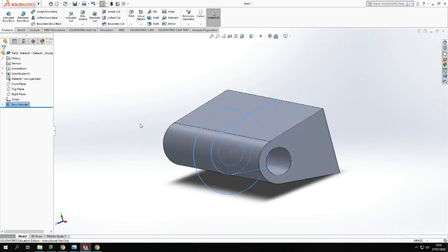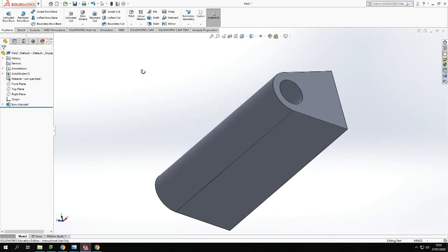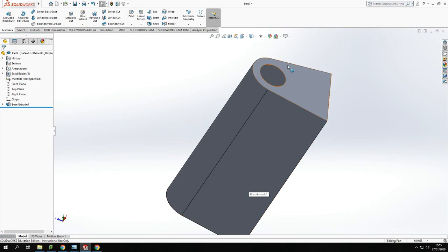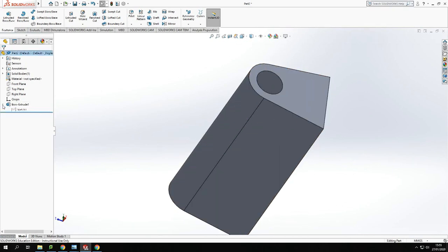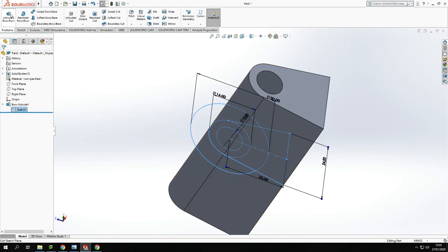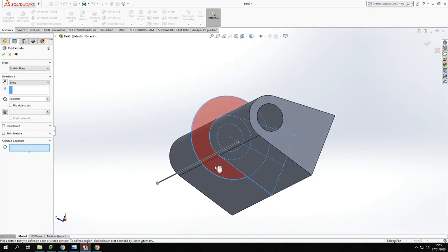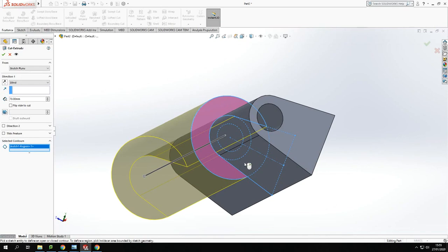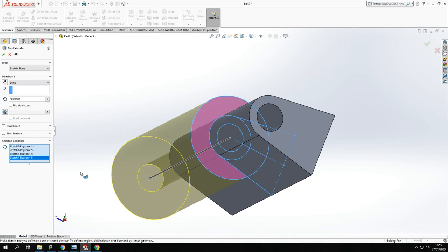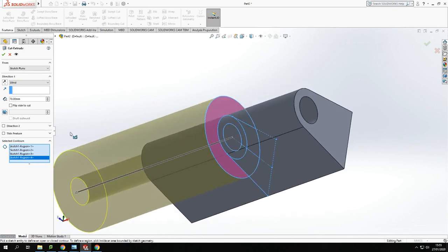and tick that. Okay, so what I've got now is the bar, a single bar effectively with the hole through the center. Now I'm going to use the sketch again. So if I just do the drop down there and use sketch 1, and this time I'm going to create a cut. Now I'm going to use the cut of this selected area here and that there. Okay, so I've just selected them sketches inside that. So I'm reusing that first sketch I've created.